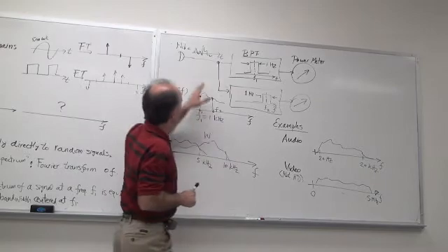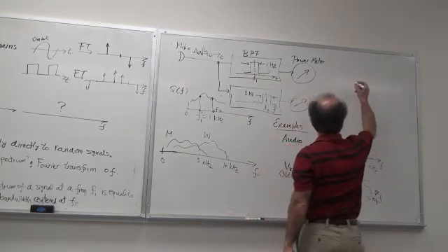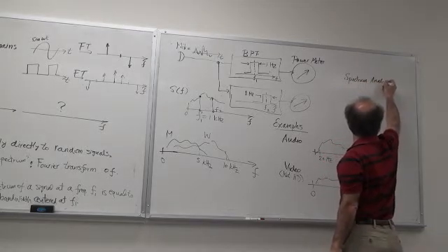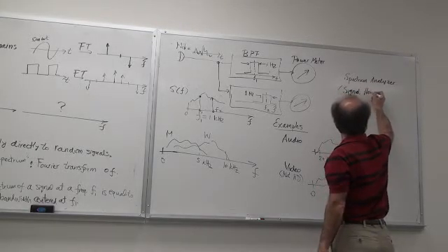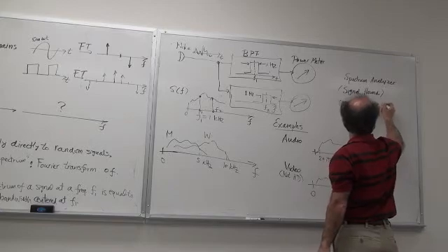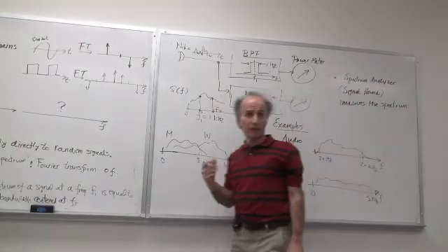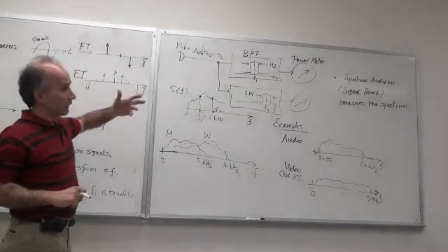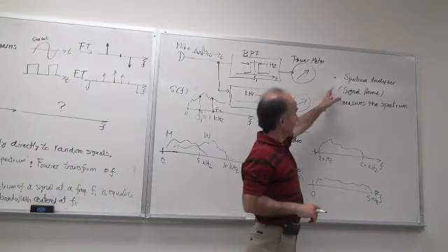The second point is that what you see here, this measurement, the conceptual measurement, is exactly done by a spectrum analyzer, which in our lab is embodied in what we call the Signal Hound, the box. It measures the spectrum. Previously, I didn't really call this spectrum, we just called it the Fourier transform, because we were looking only at sinusoids and periodic signals, right? So it was fine. We had only impulses in our observations. But today, when you look at, for example, music, then it's no longer an impulse. It has some form to it. And that's what the spectrum analyzer does.